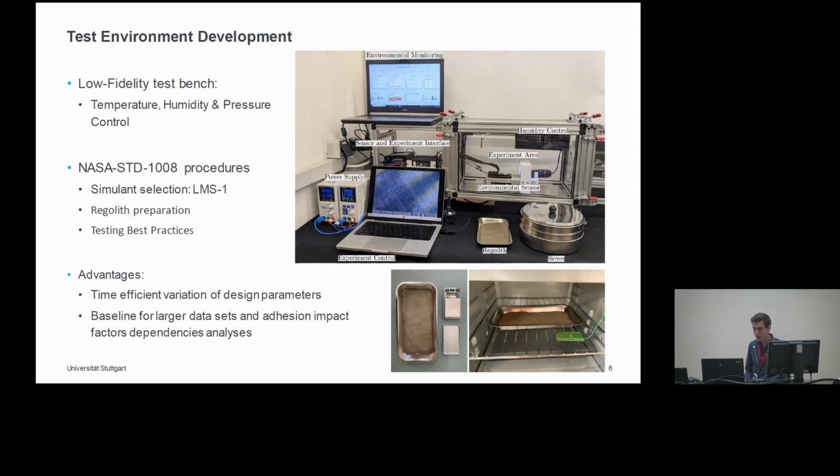This mainly reflected on the selection of the simulant. We used an Exolite simulant, the LMS-1 simulant, and the regolith preparation, a bake-out process so that the water content does not affect the result. We also follow the testing best practices of the standard.